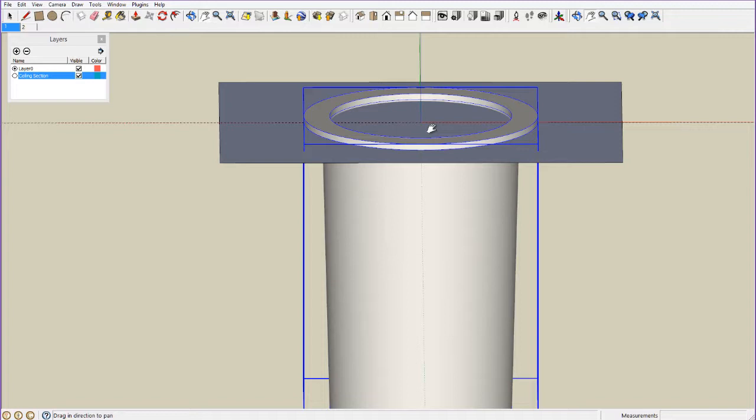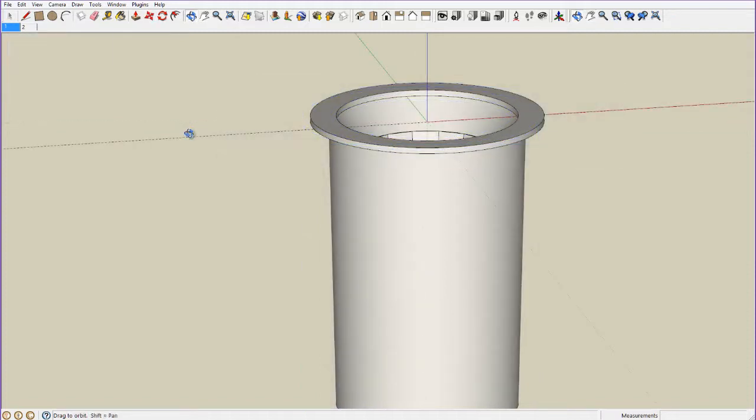Now, SketchUp has a very useful feature here which is called cut opening, and a brief explanation is that with a cut opening option selected, any enclosed shape around the center of the light fitting, but also exactly in line with the insert plane, will create a hole in the surface that it's mounted into. We want to create our shape, which is going to become the opening within the ceiling every time we put this light fitting into our scene.